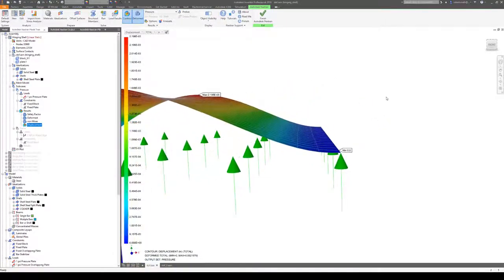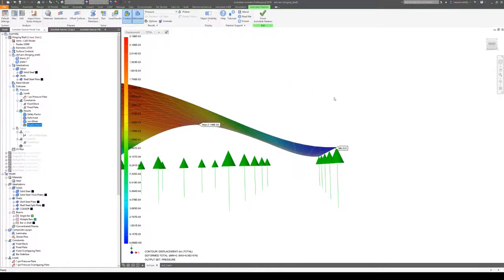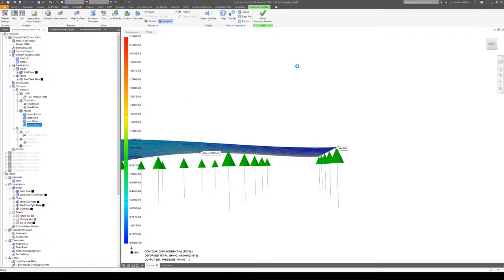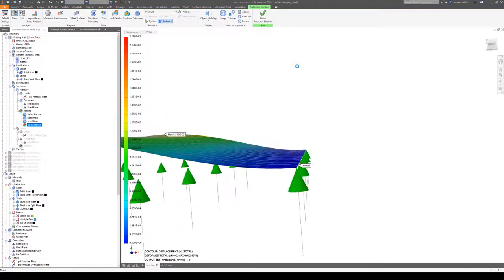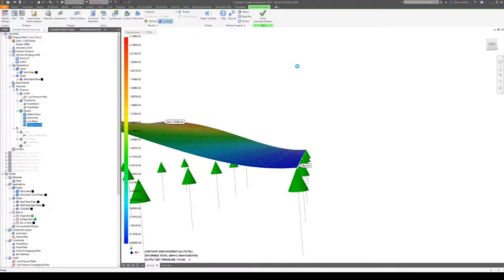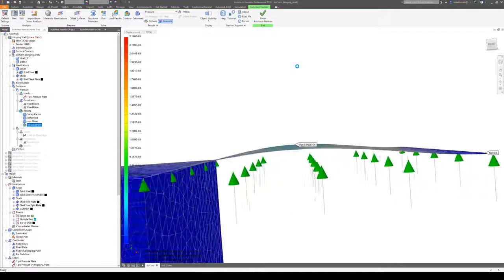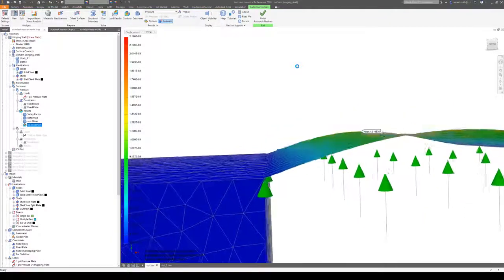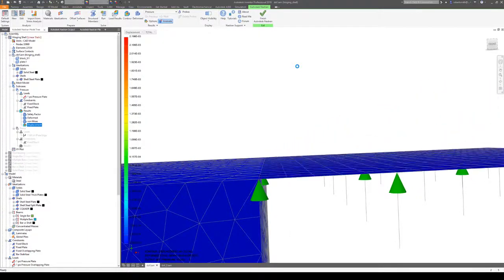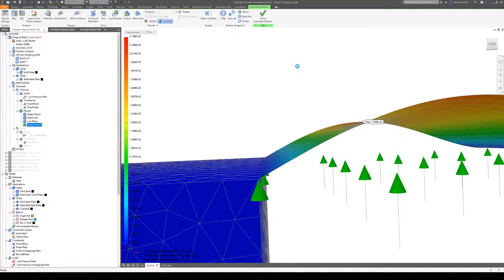If we look at the end where the plate structure is fixed, and let me get this animating so it's a bit more clear. Because the shell elements on the plate structure do support rotational degrees of freedom, when I fixed them with my constraint, it's not allowing rotation at that end. So what I get with the pressure applied underneath is bending. On the other end, where the shells connect to the solid, I do not see bending. I see basically a hinged condition. Again, because those solid elements do not resist the rotation.